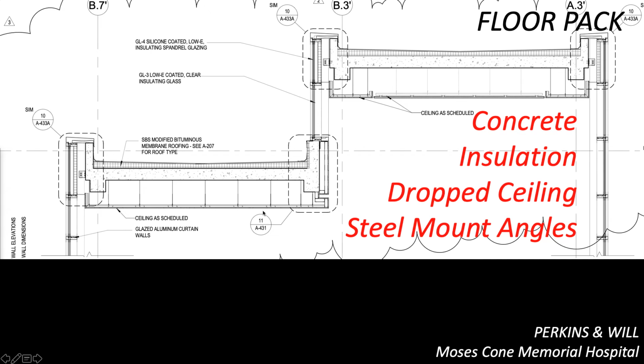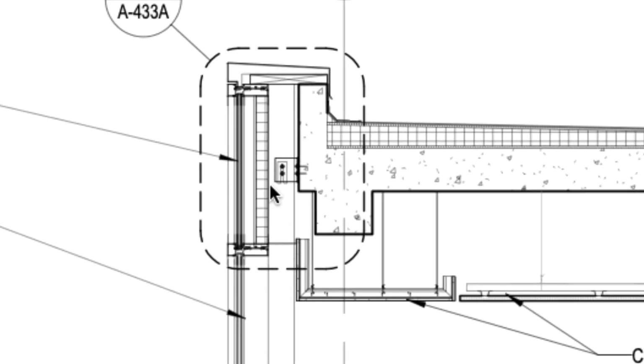This one's made with concrete. And one of the things I like about this, we see the sloped insulation, we see the decking, we see the beams integral as well as walls integral, and even a little bit of a turn up on the roof to create an area on the roof for gathering water. But my favorite part of concrete details is always where they start to negotiate with steel details. So we see this hanging device that's supported off of the edge of the concrete structural component, and that is the device that hangs the miscellaneous metals that helps us put up the various parts of the wall system.